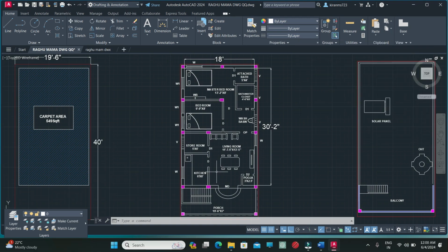Next, coming to structural criteria. In case of the structural criteria, we have to place the column in most symmetric manner as possible, and coming to individual column, we have to place the individual column in such a way that the longer dimension of the column cross section should be facing towards the maximum bending moment. How to know where the maximum bending moment is acting? We can know where the maximum bending moment is acting by knowing the span between the columns. If the span between two columns is maximum, then the maximum bending moment will be acting along that span only.